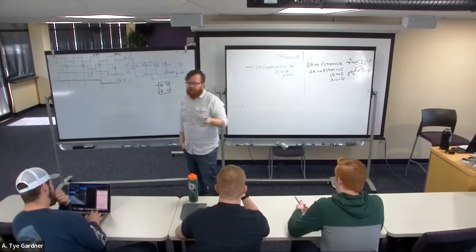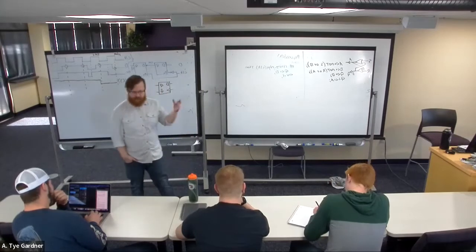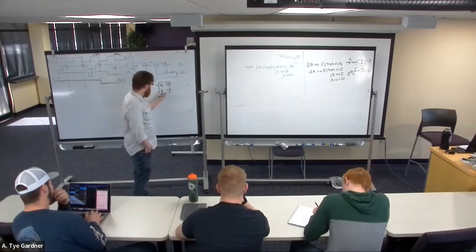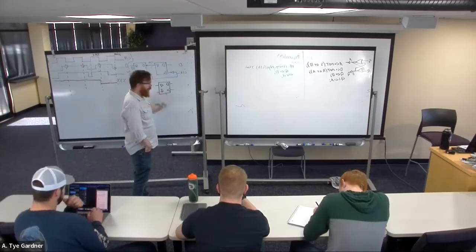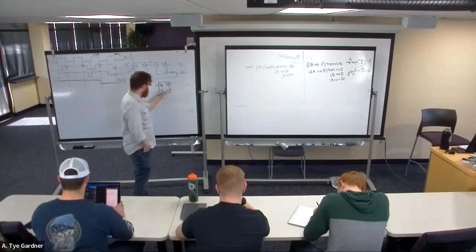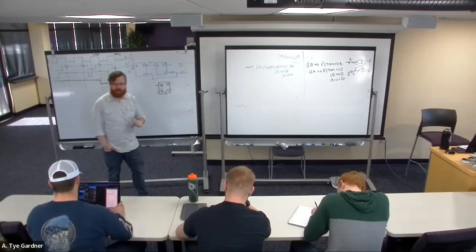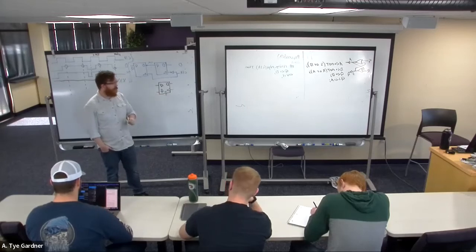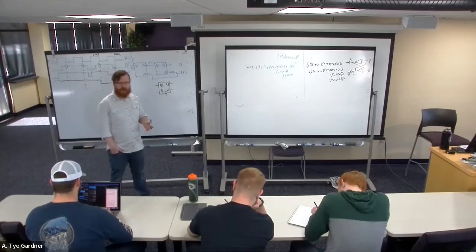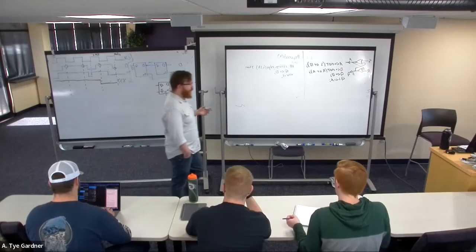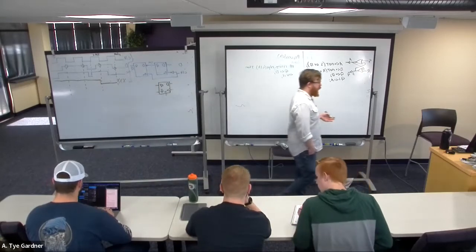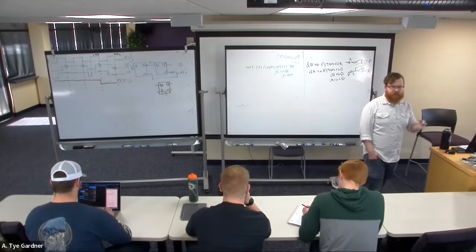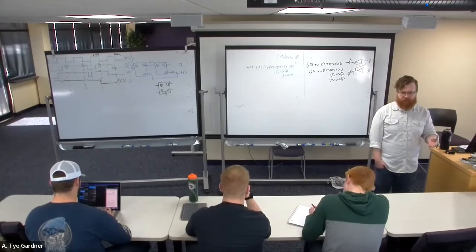Now it turns out sometimes we want to reset a device. We want to forget what it was. So I'm going to add an active low reset. This is pretty common, a signal called reset, which needs me to rewrite the code. Now resets can be done two different ways. One of them is synchronous and one of them is asynchronous.